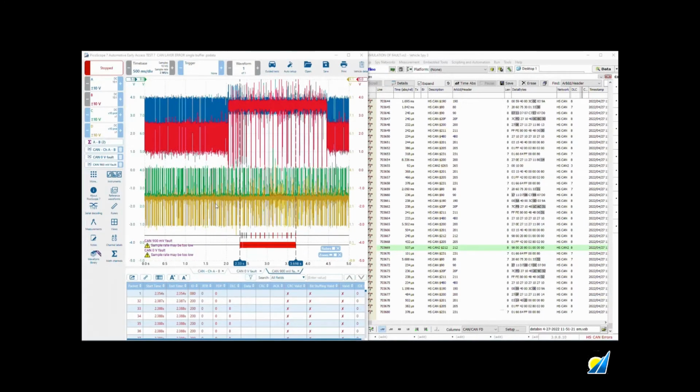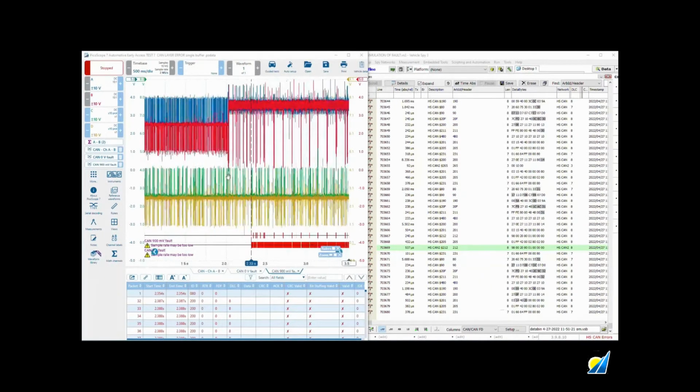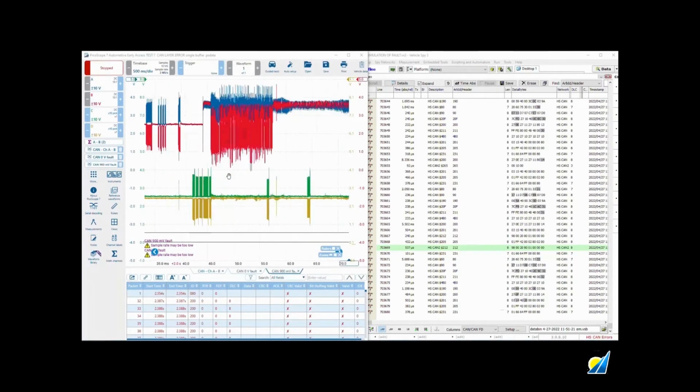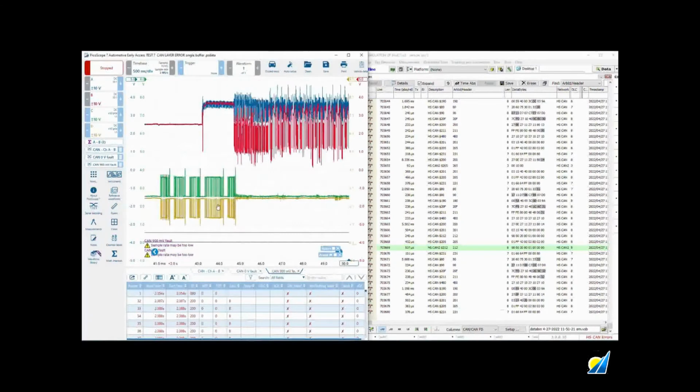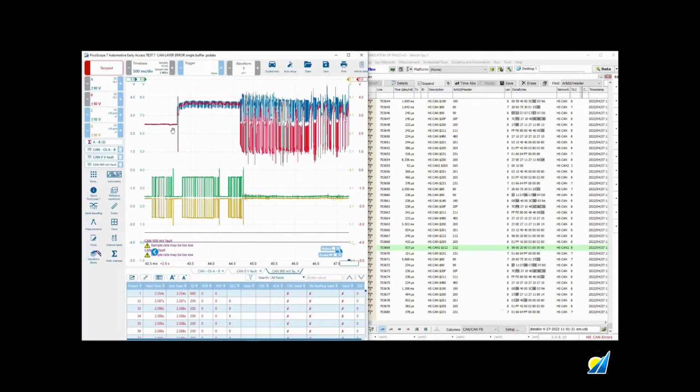And the instrument panel is the gateway for these two networks, so any exchange between the two is handled by the instrument panel. And the point to note here is that the VAN network is consistent when the fault occurs in the CAN network. So if I zoom in here, where we see the bus go high, just notice that the VAN is completely normal, so the bus on CAN has been driven high, but VAN is normal.